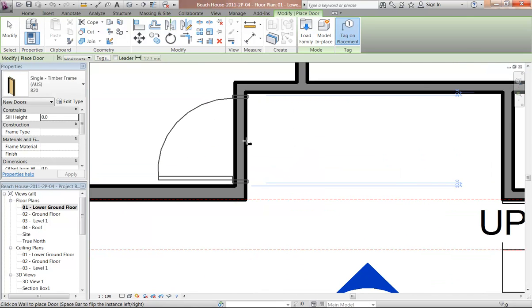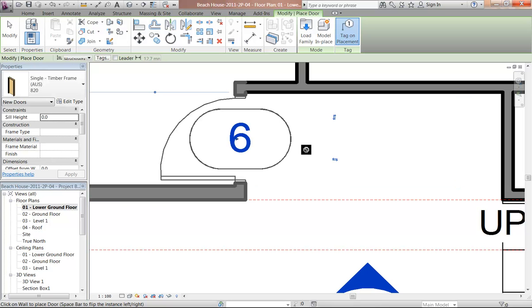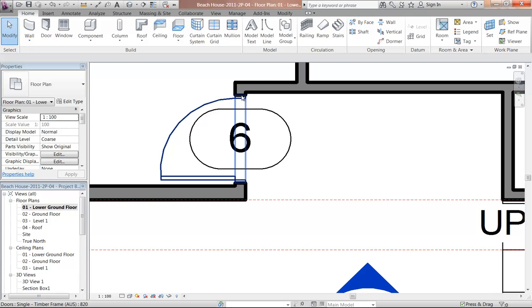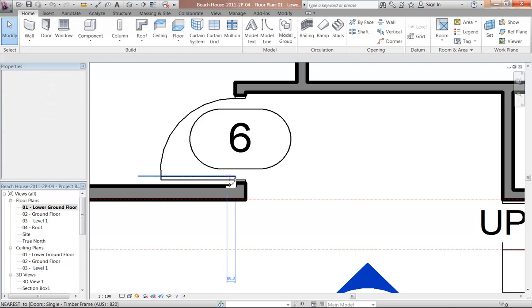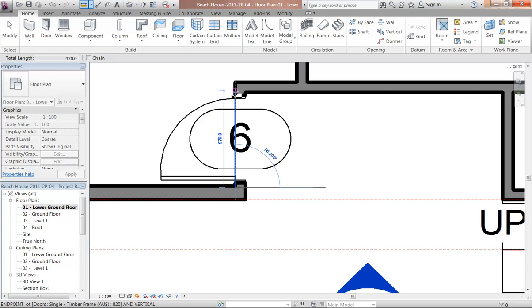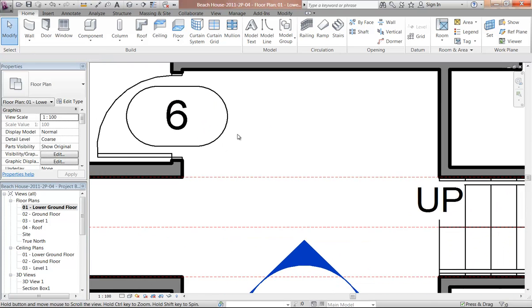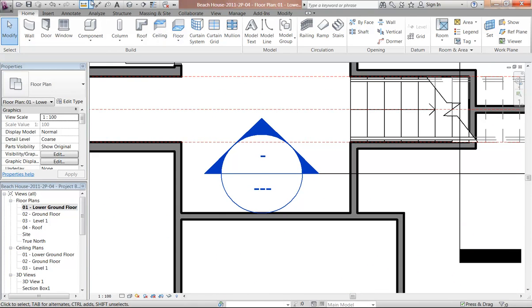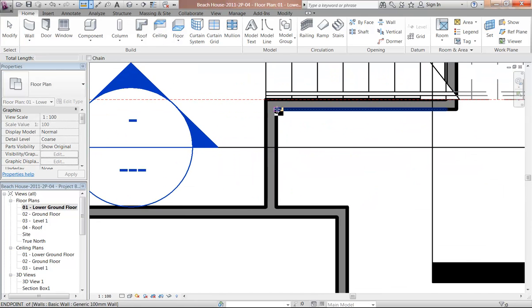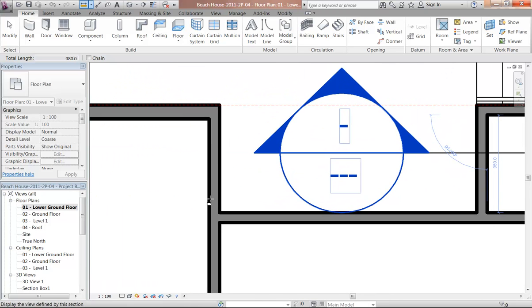So that's an 820 door, and you can see it should fit fairly well into that opening there. But there's a bit of a return either end, and on the drawings that isn't shown, so I should just check that. So here it's 955. Okay, how did that happen? Let's just see what one of the others is. If they're all the same, I'll change my door. So this one here, 980. Okay. So they're all different.